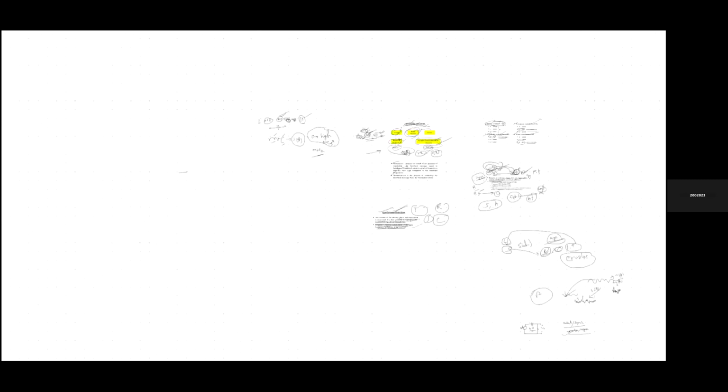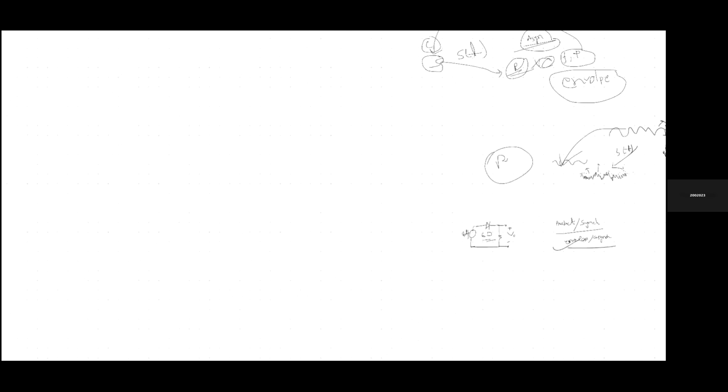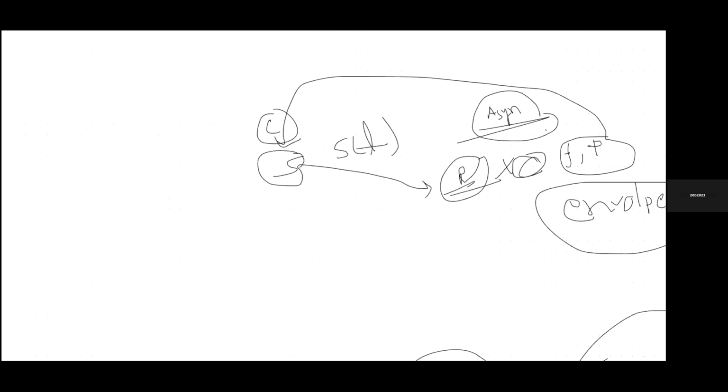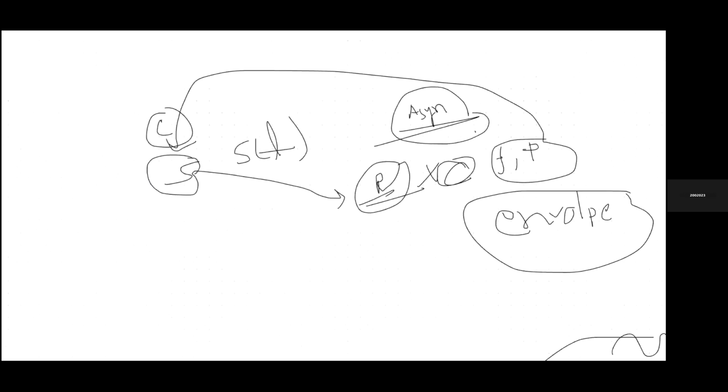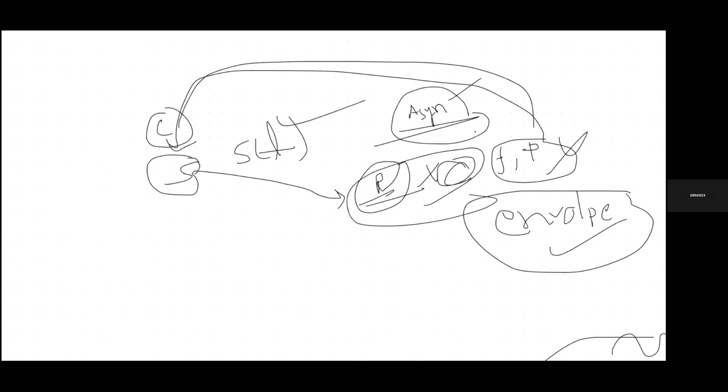So further, we can say that the asynchronous detection can be called envelope detection. How? In the asynchronous detection, the sent carrier signal will not be needed here as our reference. We only need the modulated signal to extract the main message. We will need no reference signal which will be the same in phase or frequency as the sent carrier, as we need in the synchronous detection. We will not need it here.